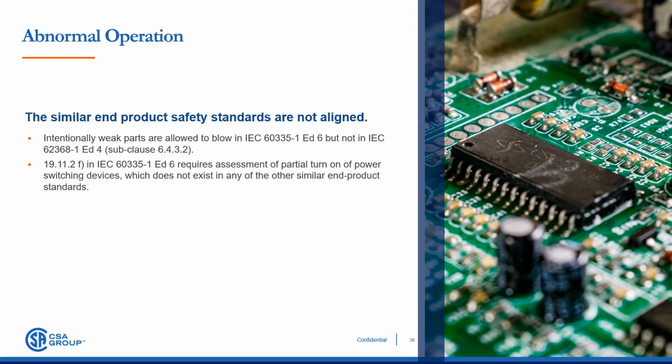Partial turn-on of such power switching components can lead to a state where other components in the circuit, whether safety-related or not, may not have enough energy to trigger open circuit conditions or reach trip limits. However, windings, heating elements, or other parts may still remain energized, potentially resulting in an unsafe condition. This slow blow consideration serves as a test to determine how appropriate safety components are when used within appliances, and if they are specified to reliably operate before any unsafe condition could occur.